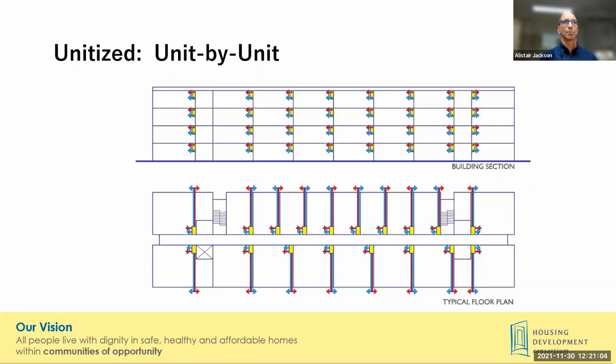The first approach is the unitized approach. This is really the straight line development from the traditional exhaust fan with trickle vents approach. We trade the exhaust fan for an ERV and the trickle vents for supply ducts. Each unit has its own ERV, typically located in a drop soffit above the entry or in a bath above the bathroom. There's no roof penetrations, no shafts, no complex coordination of ductwork in the corridor ceilings, and the ERV is on the unit electric meter, not the house meter.